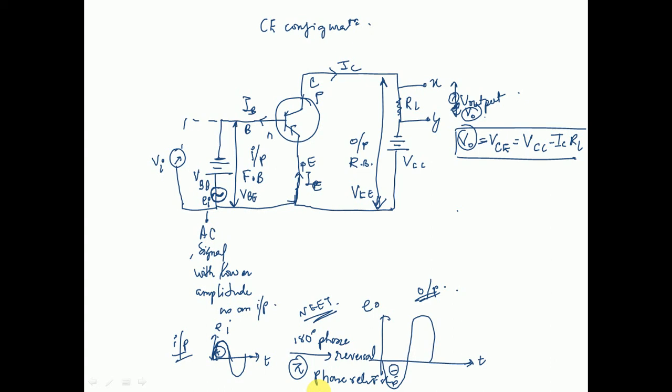When the AC signal is fed to the input circuit, its positive half cycle increases, and that in turn increases the forward bias of the circuit. Yes or no? The forward bias will also increase. This increases the emitter current because the base current IB increases.